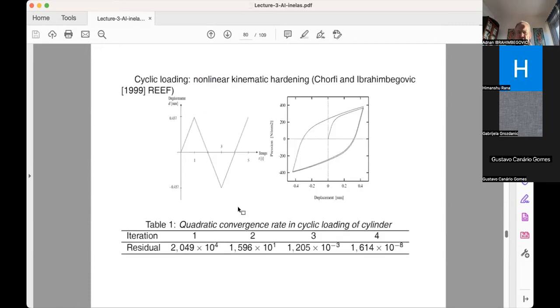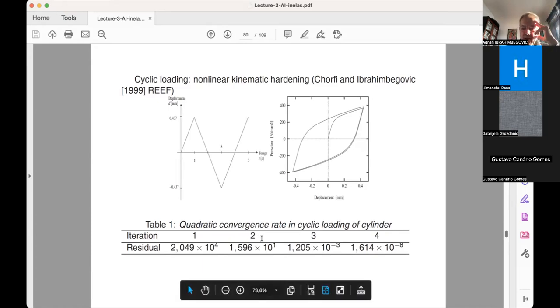One of my doctoral students, Lotfi Chaabane, was working on cyclic loading plasticity and basically used something called the Frederick-Armstrong model, or in France called the Chaboche model, for which you have a really wonderful hysteretic slope that you can control in terms of stability and always keep the same value as we go along. And we were able to get the quadratic convergence. You can see that when you go down to zero, the number of zeros keeps doubling and so on and so forth.